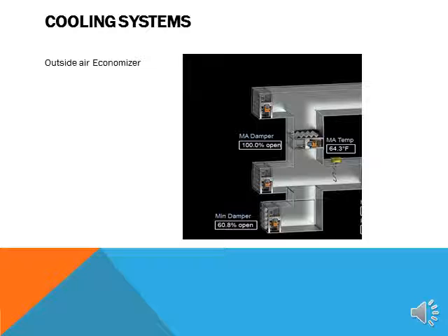How this works is we take the outside air through the supply air fans, draw it into the building, therefore sending it down the ductwork to the spaces to be used for cooling as required. The air is then brought back through the return air system and is either brought down through the return or mixed air dampers or is exhausted from the building.